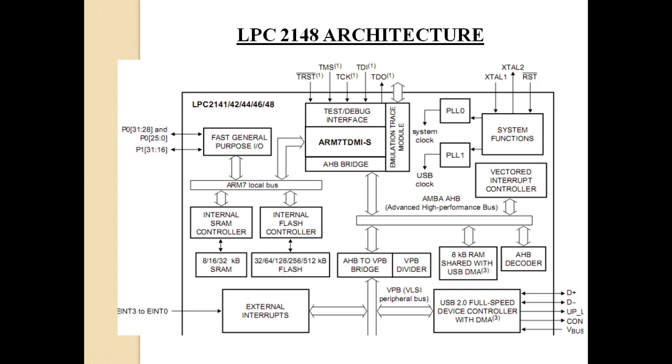So initially, in the olden times, where was the program stored? It was stored in a device known as ROM, read-only memory. What is the speciality of that? You can only read from that. You cannot write into that. After the invention of the ROM, they developed something known as PROM, programmable ROM. That means you can write to that ROM only once, then you can read from that, right? So that writing process will be done in the factory itself. That is known as PROM, programmable ROM.